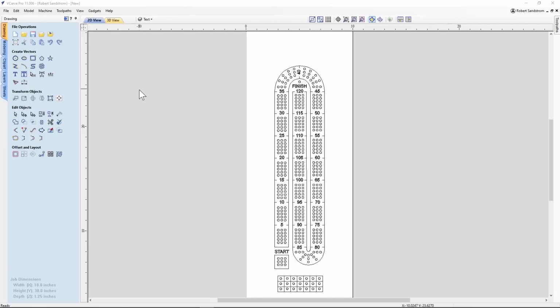So the first thing we want to do is recognize there are two sizes of pegs used in a cribbage board. The typical small size peg is a 1/8 inch peg, and it's typically anywhere between a 1/2 inch to a little longer deep. The other peg, which people like, is a 3/16 inch peg, which is a bigger peg and used for bigger cribbage boards, and it's close to an inch deep, about 0.95 inches or so if you want to bottom it out at the shaft.